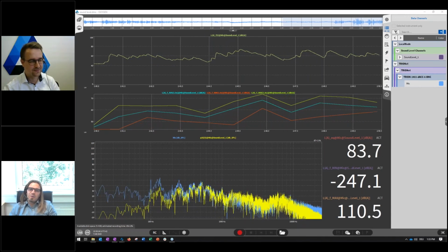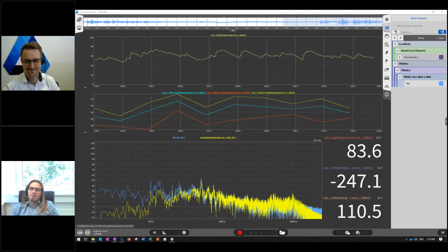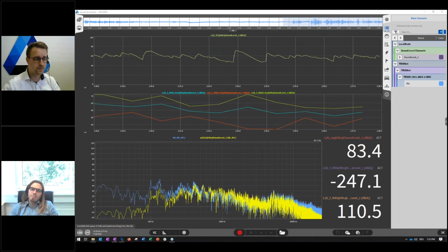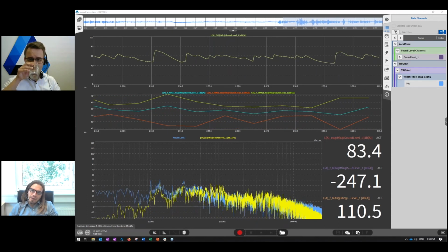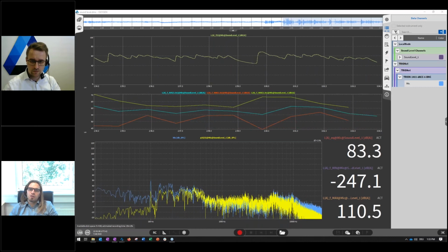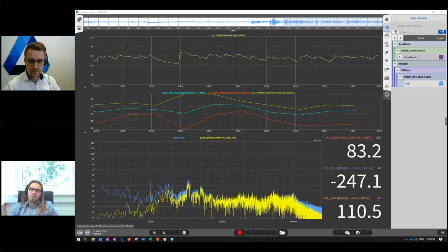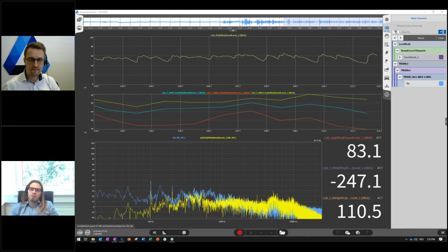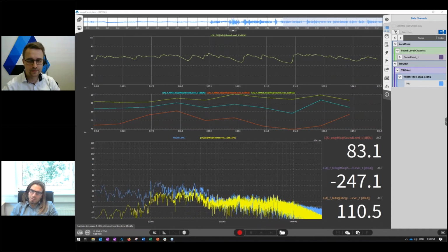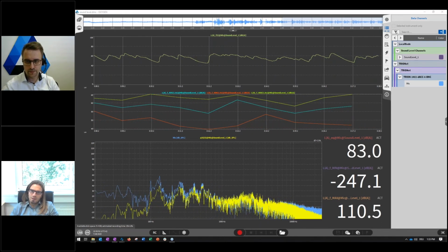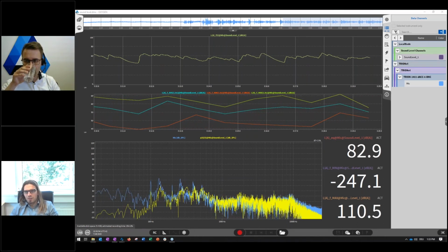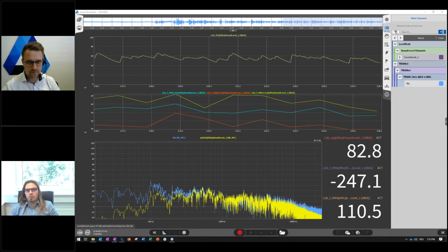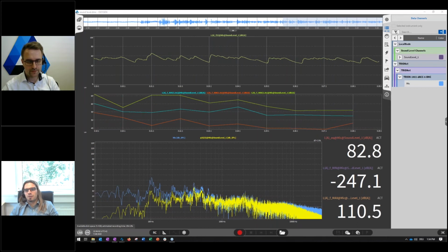On the one hand, we are now supporting the Vector VN series, the VN hardware series from Vector, to acquire FlexRay and CAN FD data streams in Oxygen. So the VN series has data interfaces for automotive buses, which are connected via USB to your measurement device, and you can use the adapters of the VN series to acquire and decode CAN FD and also FlexRay data streams in Oxygen, and to synchronize them to your analog data if it is required.